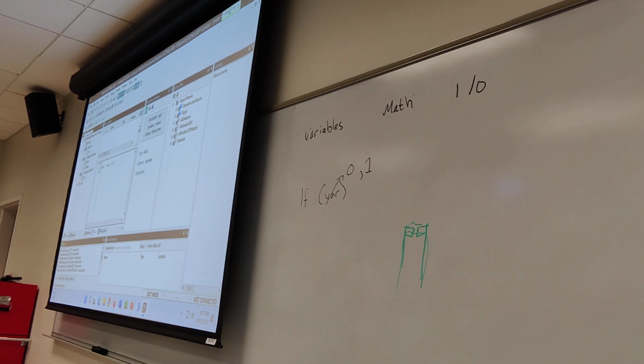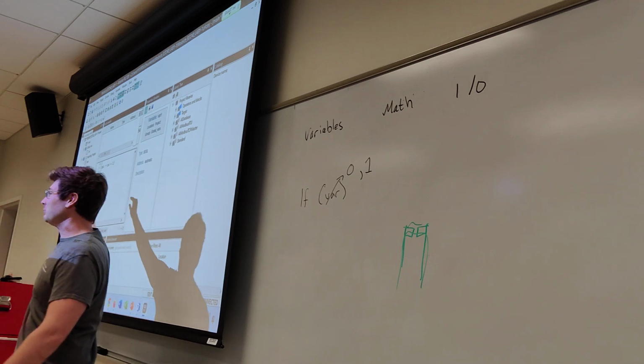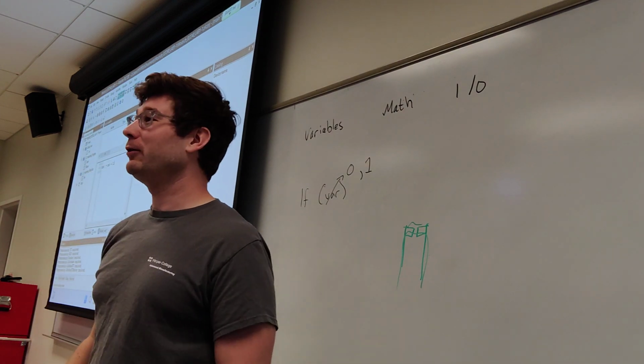So click this button that uploads the code. What that did is it's compiling the code, which means that it's on the PC, and then it will upload the code, which means that the code will be on here. It looks like you didn't do the compile sketch earlier. So that's why I said to click this button earlier, because this is going to take a few minutes. Once that's done, it should upload code, and then when you hit this button, like you were trying to hit before, you'll actually be able to click it, and then you'll see more come up. Anyone else? Any questions?